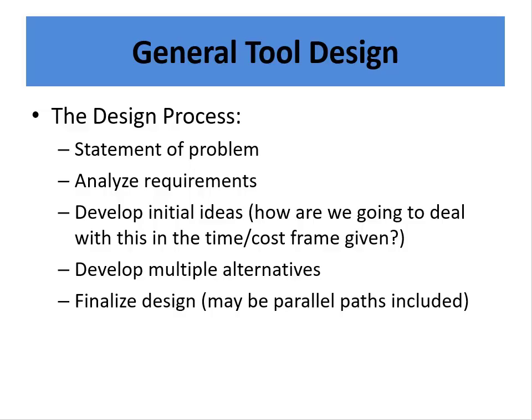So if you're going to do a quantity of parts that is maybe smaller and you want to get it up and running quickly, you might machine something, and maybe long term you would cast it. But maybe the material and the tooling for the casting would take longer. So you'd have a short-term solution, and as the project grows, maybe you roll it into a long-term solution or something like that. And then finalize the design.